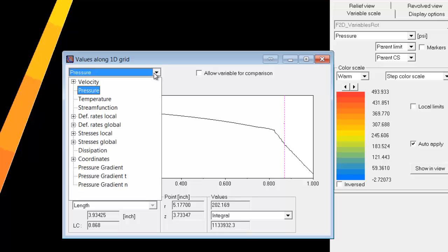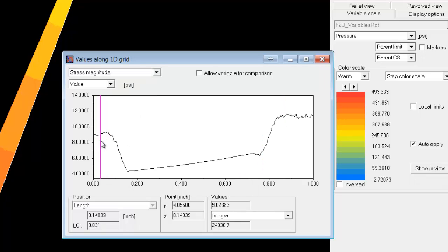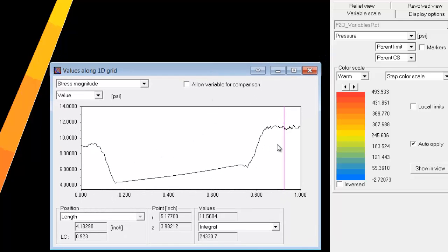Now on this surface we can also look at the shear stress, and we can see that the shear stress is relatively high where the gap is small, and then drops where the gap increases down to a value of about 4.3, and then gradually increases as that channel gap is getting smaller, and then increases up again to the shear stress in the die lips of about 11 psi. So that looks relatively good.